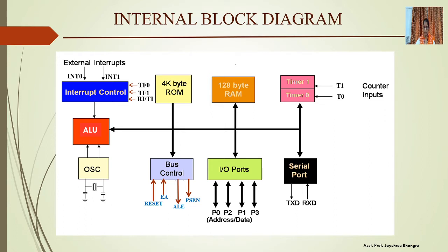The clock generator is an integral part of the microcontroller and the user has to provide the additional timing circuitry in the form of a crystal. So this is nothing but the crystal. We can connect different frequency crystals to the oscillator. The range of crystals we can connect to the oscillator is from 1 MHz to 20 MHz. If we want a higher speed of operation, we can connect a higher frequency crystal to the oscillator.